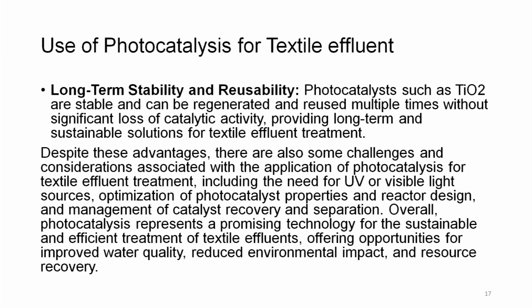Long term stability and reusability. Photocatalysts such as titanium dioxide are stable and can be regenerated and reused multiple times without significant loss of catalytic activity, providing long term and sustainable solution for textile effluent treatment. So, here first it is not generating any sludge, or secondly very minimal sludge, and the chemical that is used can be reused, recycled with the same effectivity, but just by regeneration.